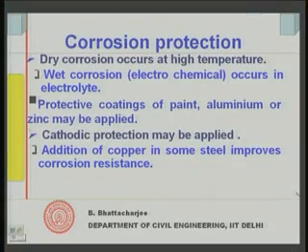But stainless steel cannot be used in structures except in exceptional cases, because it is relatively very costly. But in exceptional cases one may use even stainless steel, which does not corrode, because it is the exposure condition which will dictate this use. So, that is about corrosion protection.